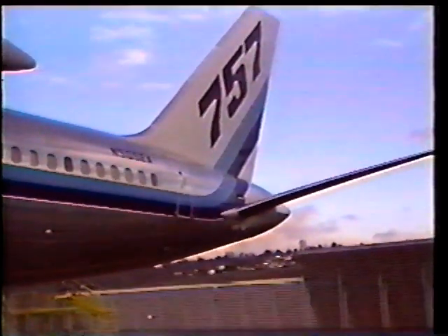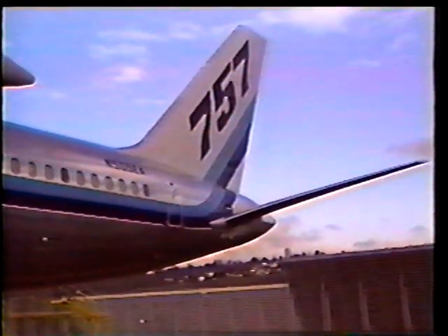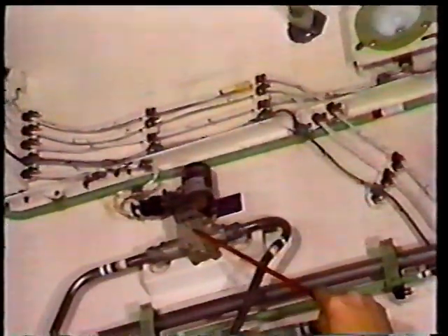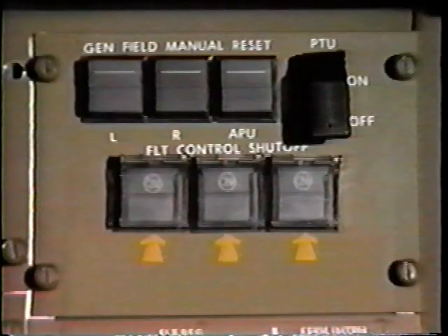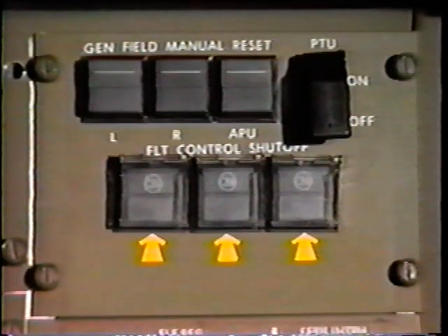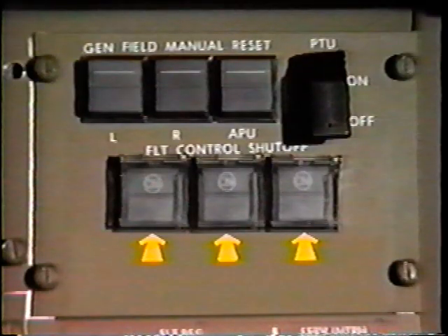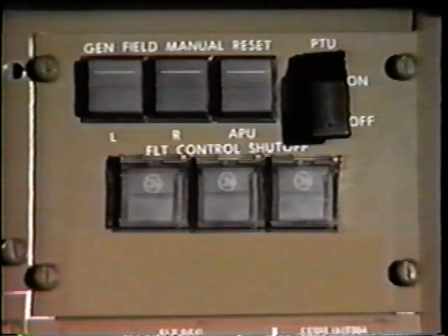For maintenance troubleshooting, each hydraulic system contains an isolation valve that shuts off fluid to the tail hydraulic components. Located on the aft wall of the right wheel well is the right system isolation valve. The left and center isolation valves are located in the left wheel well. Located on the aft wall are the left system isolation valve and the center system isolation valve. The control switches for these three valves are located on the P61 maintenance side panel. The switches are active when the airplane is on the ground.